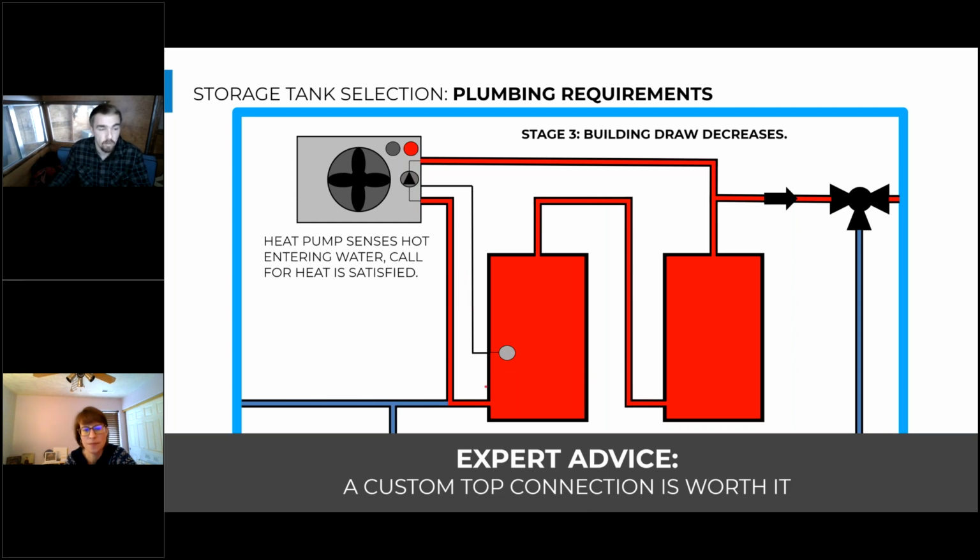So if you turn off when this water is maybe just slightly warm or even still cold, based off a sensor up here, then you can mitigate any challenges that that specific manufacturer has with high entering water temperature. Otherwise, you do see a lower efficiency in these heat pumps that can still handle the higher entering water temperatures if you turn off later, but it's just that really small fraction of time where your storage is completely charged and your heat pump's about to shut off. So in the overall scheme of things, the efficiency hit you would see from that is really negligible.